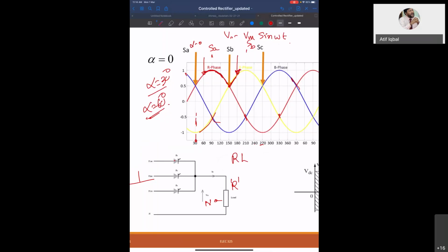And as you know, even if the voltage across them is high, if you do not apply the gate pulse, it will not operate. So it will keep on conducting until this point. When you trigger the next at this point, then it will start conducting. Do you understand this point, Hane? Yes. Does that answer your question?